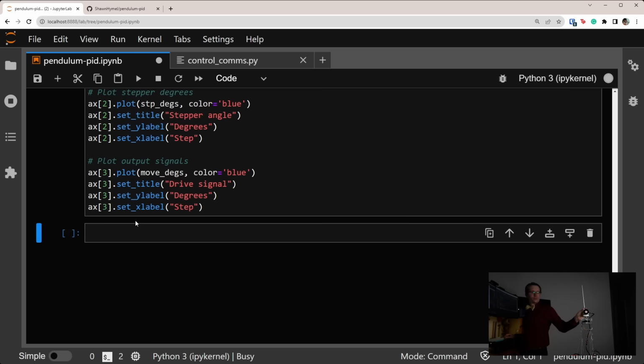And just so you can see what happens when we really crank this up, let's take it to 5 and really try to make this too high. Yeah, there we go. We're getting too many of the oscillations and it's pretty unstable. It can't control it. So that means we are suppressing Ki and Kp a little too much. And sure enough, you can see it with this encoder angle. It's struggling here. Okay, so we know we got to be less than 5.